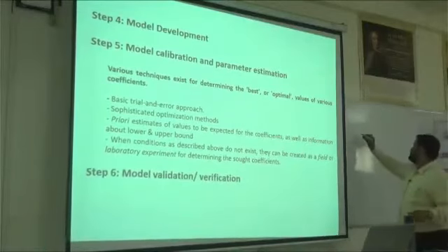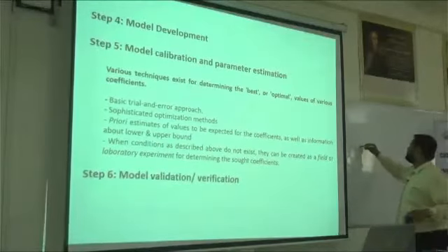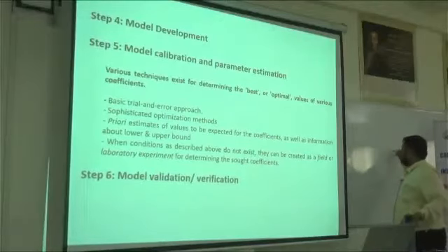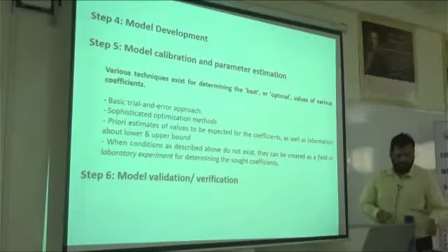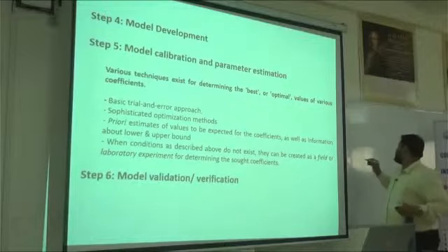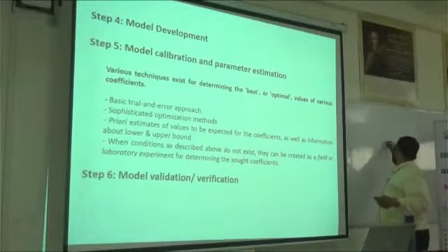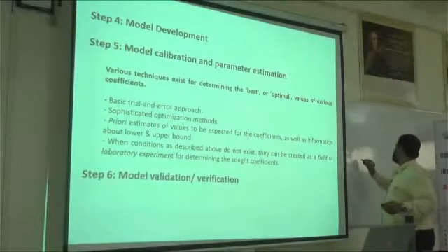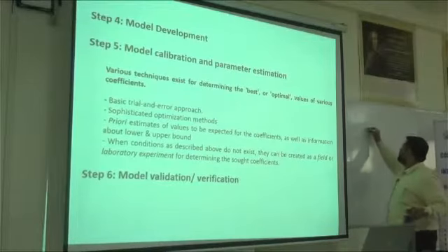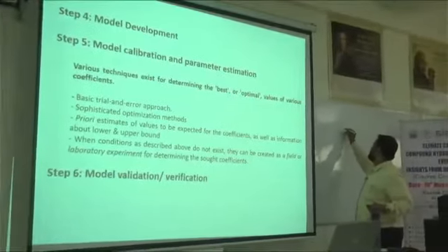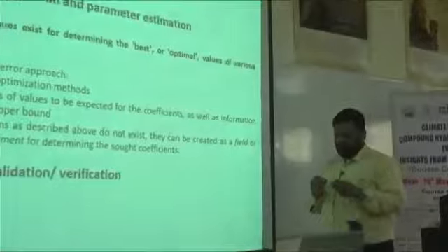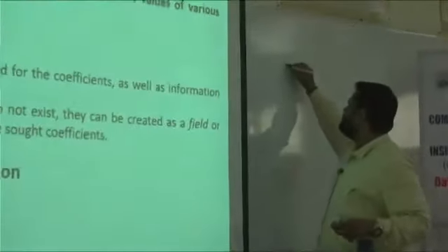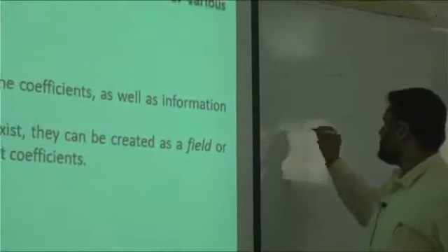Like that, you have to plot these types of hydrographs between your observed and simulated data. You might have seen all these types of graphs in research papers. This is your discharge versus your time curve. Suppose this is your observed data and this is your simulated data. You have to identify what type of gaps you are getting, or whether some kind of shifting is there.